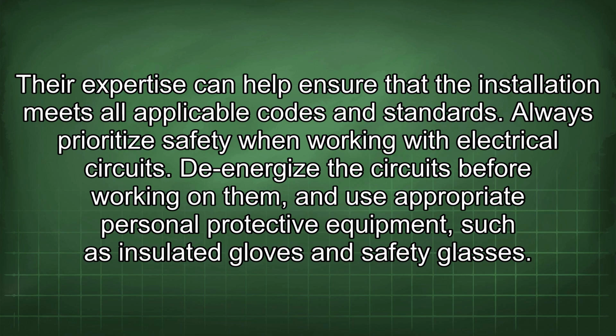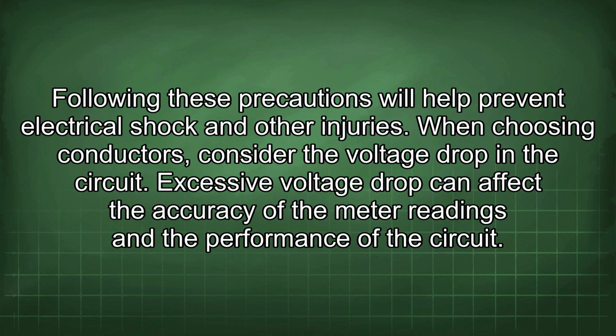Always prioritize safety when working with electrical circuits. De-energize the circuits before working on them, and use appropriate personal protective equipment, such as insulated gloves and safety glasses. Following these precautions will help prevent electrical shock and other injuries.